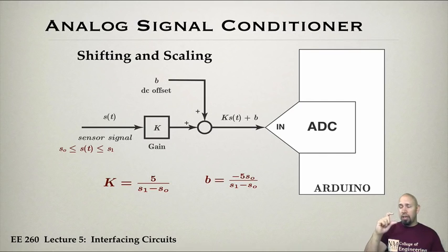And I should have put that on here. The Arduino doesn't do negative voltages. So you can't go minus 5 to 5 because the Arduino won't handle that. So you have to shift that whole range up so that it still fits within 5 volts, from 0 to 5 volts. So we basically need to transform our input from plus or minus 10 volts, from anything in that range, to something in the range of 0 to 5. We need to transform it. And so basically